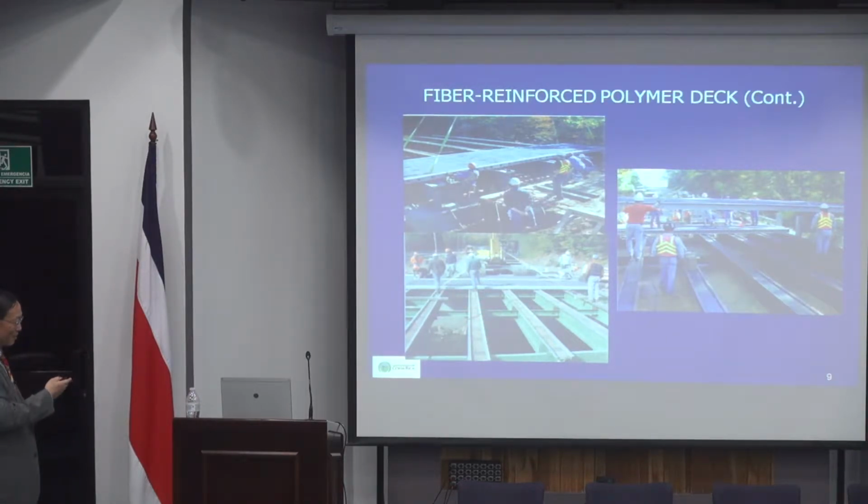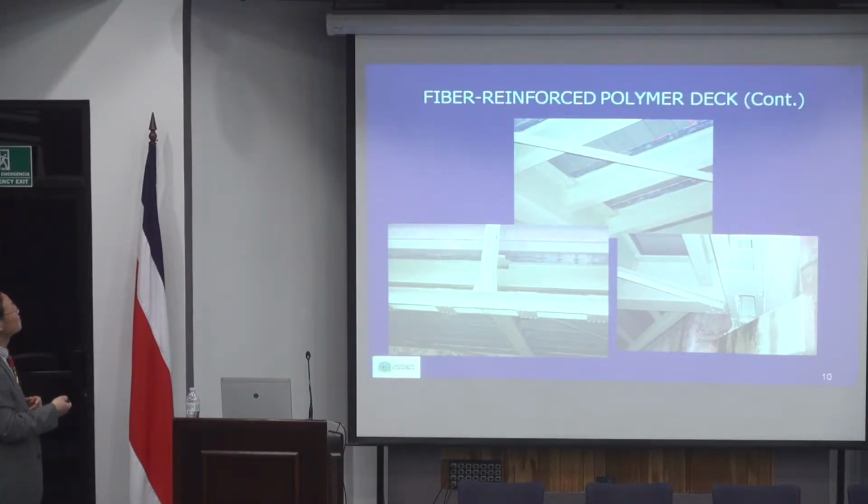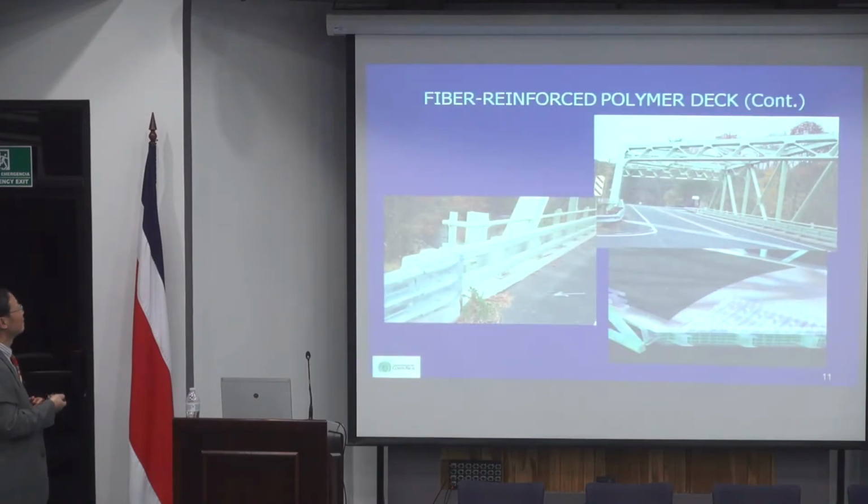What you can do is weld very light gauge angles to the top of the flange edge to make up the height difference, so that it will be totally flat. From underneath, you will see these panels look very neat, like plastic. That's the final product. That's a bridge.